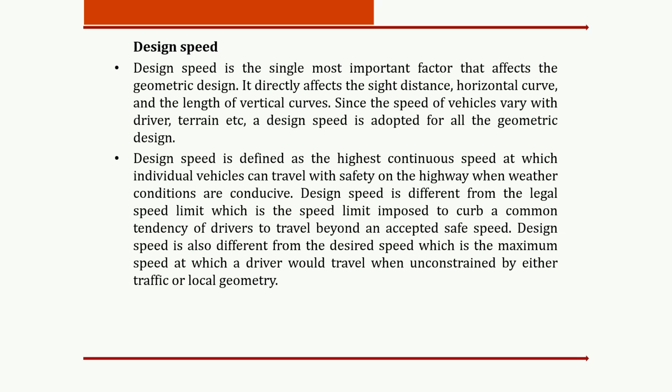So basically in simple language, if I want to tell you what you mean by the design speed, design speed is that speed by using which the driver can properly drive his vehicle on the road and there should not be any chances of accident. So design speed plays a very important role for the road construction. Design speed is defined as the highest continuous speed at which an individual vehicle can travel with safety on the highway when weather conditions are conducive.